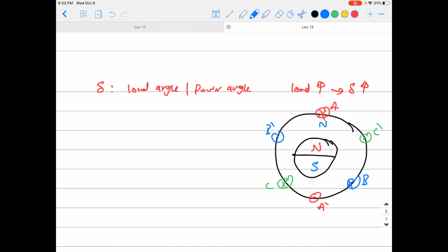Those poles, a north pole, a south pole, a north, a south, are rotating because, like I said in the last lecture, a three-phase winding is fed from a three-phase supply, meaning three-phase currents move in the winding. Those poles will be rotating around the circumference of the stator at the synchronous speed, 120 f/p. Okay, guys?